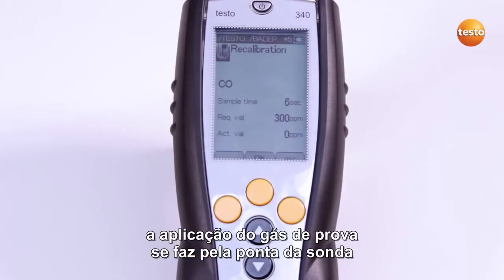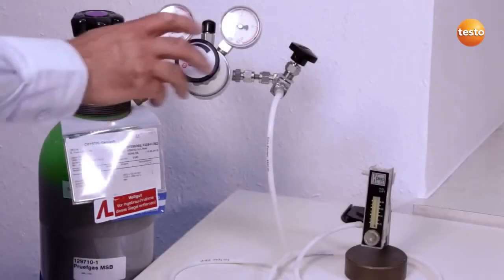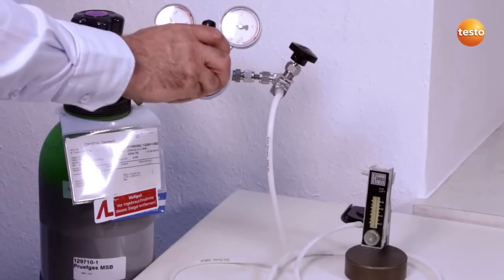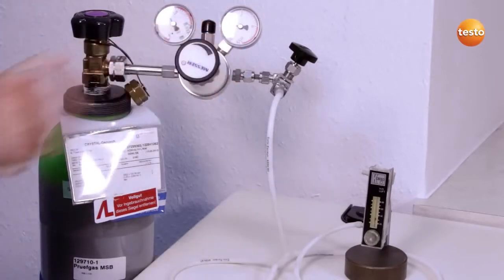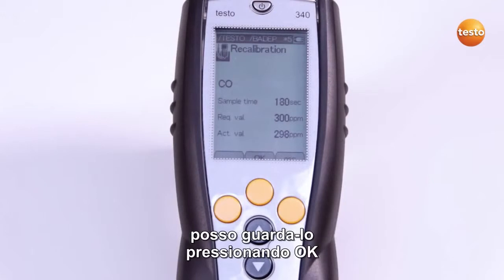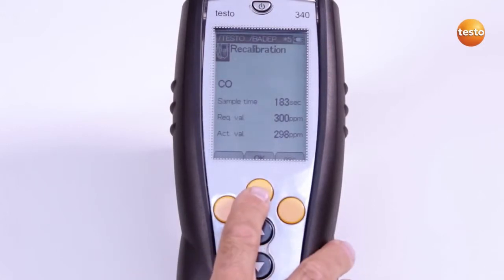The test gas is admitted via the probe tip. Alternatively, the service adapter can also be used. The sensor is now supplied with test gas for 3 minutes. For this, I open the test gas bottle and apply the gas pressureless via a bypass. As soon as the actual value is stable, the value can be saved by pressing OK and the sensor is recalibrated.